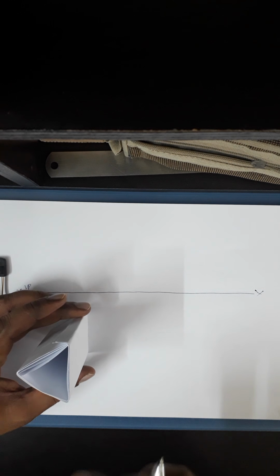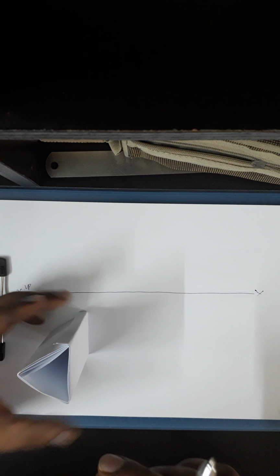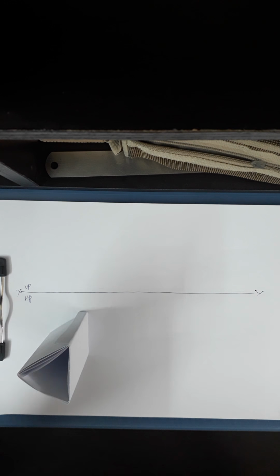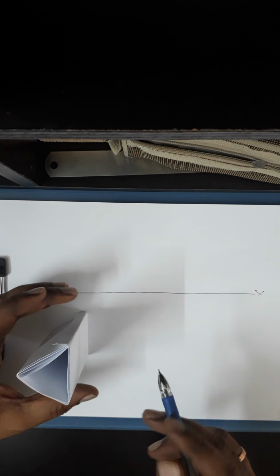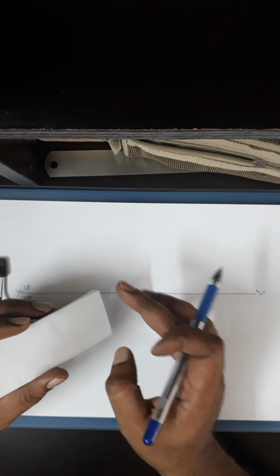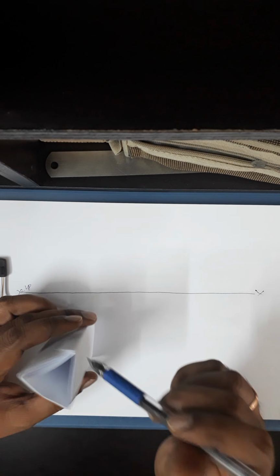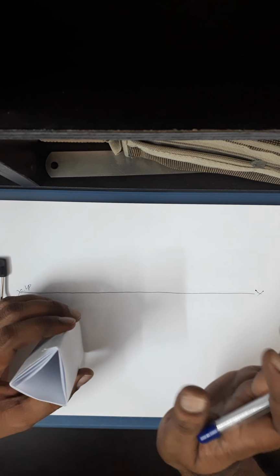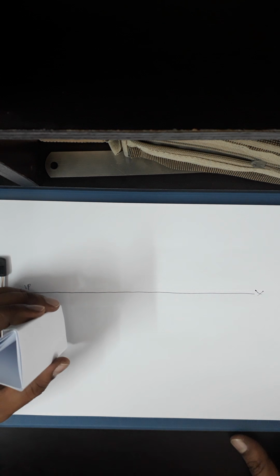Having one of its base edges resting on HP with the prism having its axis inclined to HP and parallel to VP. So then I can create a problem something like this. A triangular prism of 30 mm base edges and a height of 60 mm is resting on one of its base edges on HP such that the axis of the prism is inclined at 30 degrees to HP and parallel to VP. Draw its projections. Okay. So that is the problem. And I'll explain how to draw the solution for this problem.